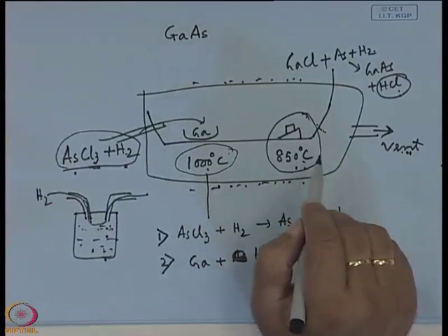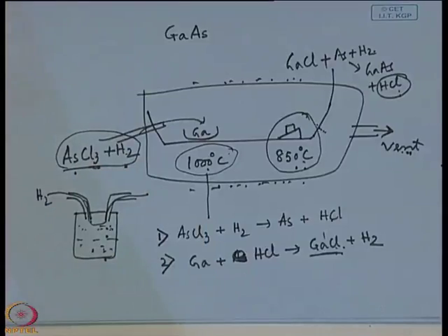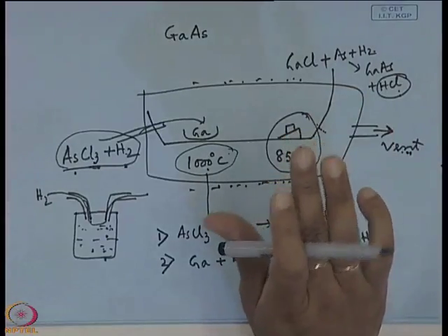I shall show you one chamber of CVD in my laboratory. So, all those things it will be much easier for you to feel. Where is the gas line, where is the inlet, where is the outlet, where is the pump put, where is the susceptor, how the susceptor is put inside the reactor chamber, how the substrate is kept on the susceptor. And more important is how you can control the various kinds of gases, because until now we have not discussed any controlling parameter.